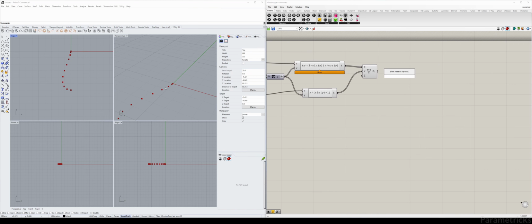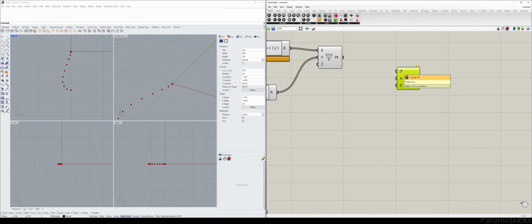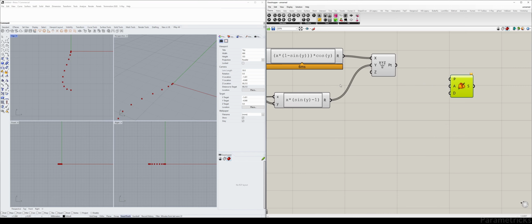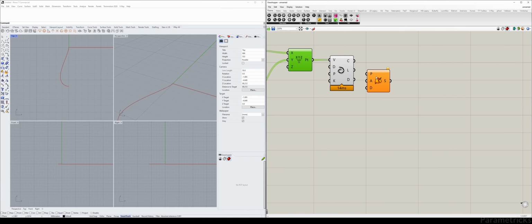So first off, to revolve, I need an axis, because the revolve command needs the profile curve, which we'll create right now. So we're going to make an interpolated curve, which will be this one. So we draw that. We don't need to see this now. You can see that's quite a nice looking half of a droplet. And this will go in here.